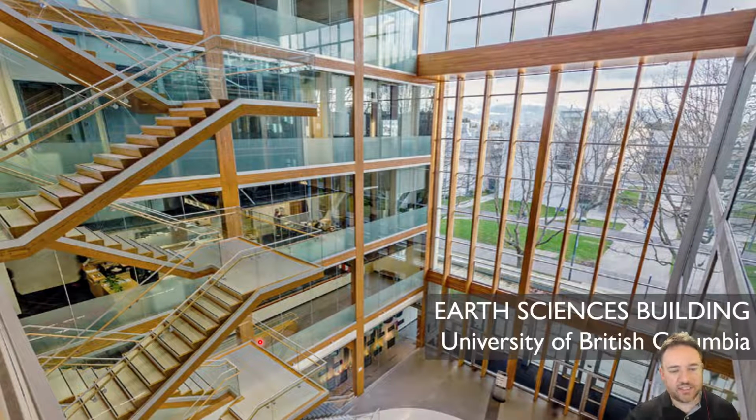So this one has been around for a little while now, but it is a very famous example of innovative timber construction, which is actually a hybrid building, the Earth Sciences building at the University of British Columbia. This building's lateral load resisting system is not timber, but a lot of the gravity load system in a lot of parts of the building is timber, and you can see some really nice tall columns and window mullions and post and beam on the left, and this really snazzy feature staircase, which is actually cantilevered out from the edge of the stair.